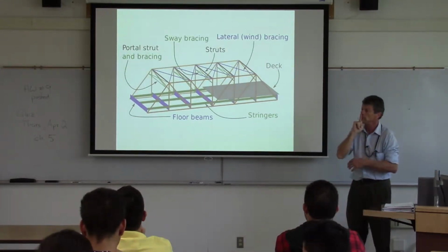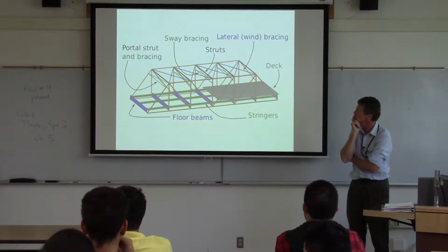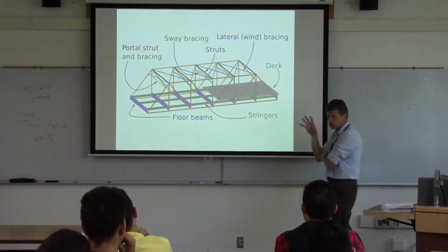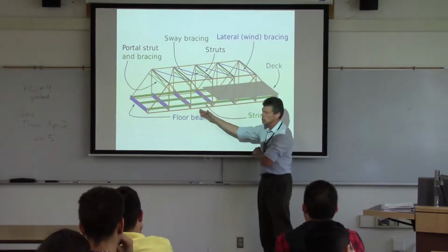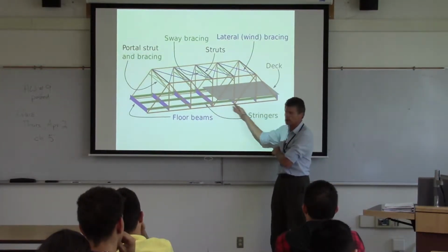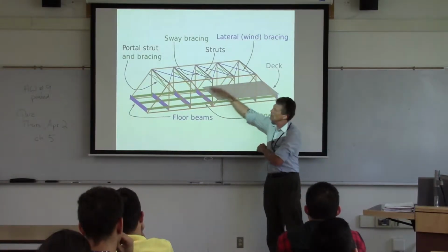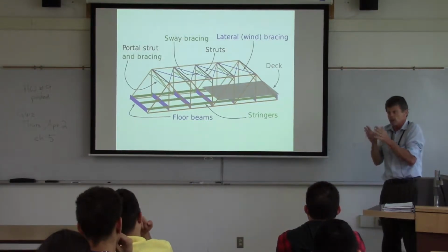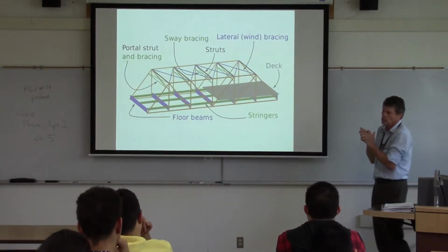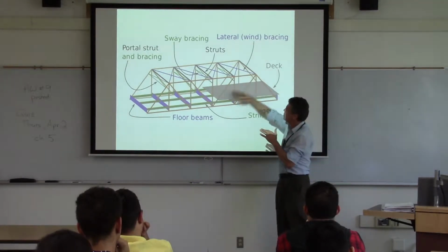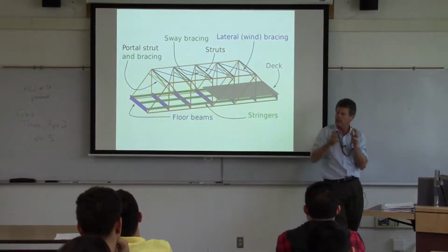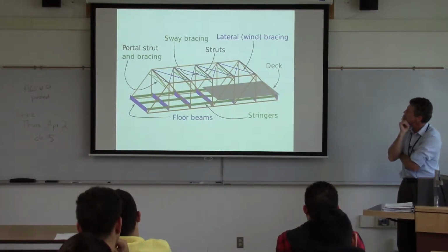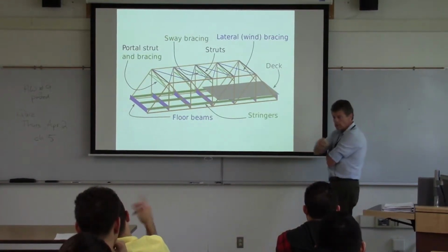Question? Is the purpose to increase the tensile strength of the bridge? Well, it's kind of going that way. What we're going to be doing, and we'll see this when we start looking at simply supported bridges, is that the bottom will be in tension and the top will be in compression. And this will be something you'll be doing when you get into mechanics of materials, because we're going to see the same effect in beams too. And basically what it's doing is pushing the material out, so we don't need as much material to carry it if we can carry it further away.